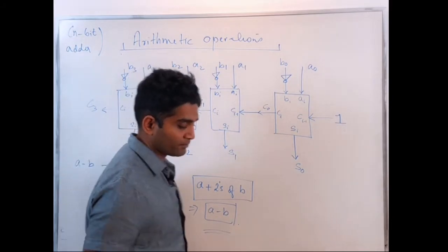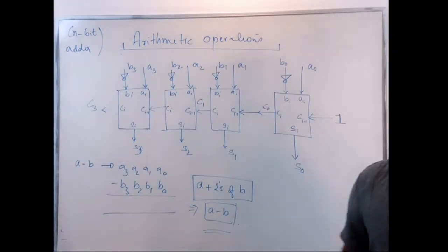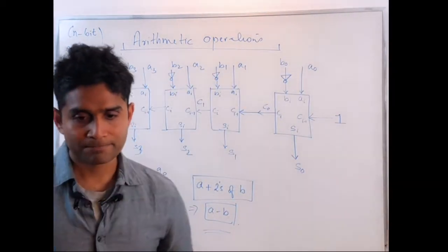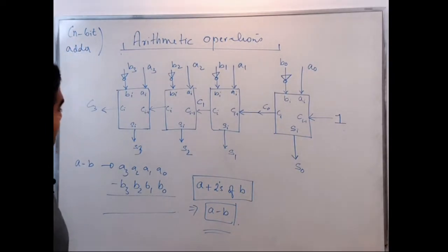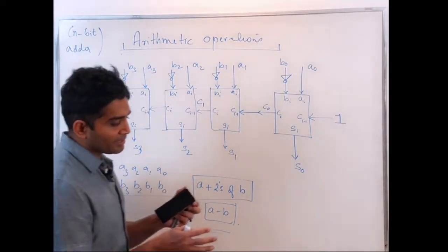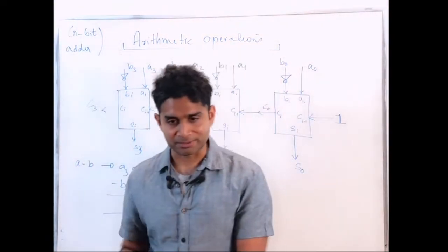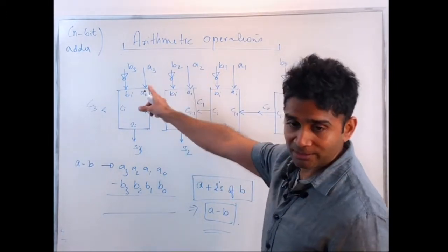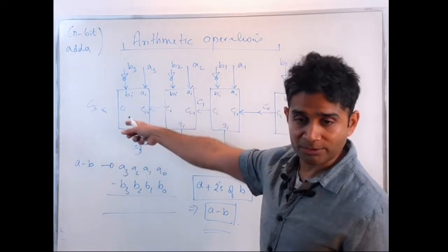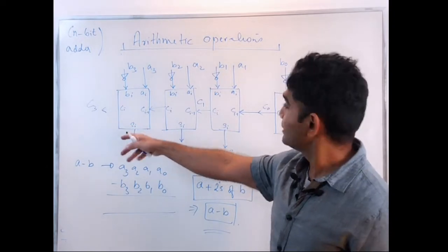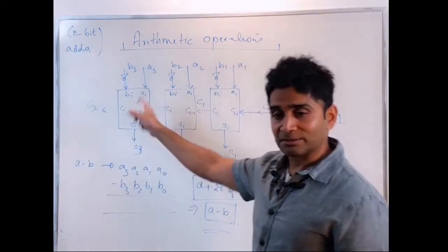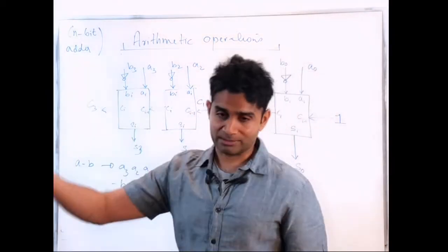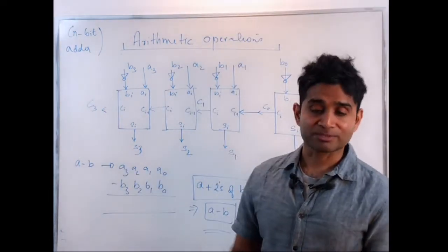So now I have developed, constructed a subtractor circuit directly from the adder. Okay. So that's very good. But still, the problem is I still need a separate subtractor circuit, a separate adder circuit here. I want to do those operations, A plus B operation. Once I do this modification here, I will not be able to use this for addition operation. That's a subtraction. If I don't do this complement operation, this is going to do the addition operation. Right? But what if I want to do both, depending on the circumstance?